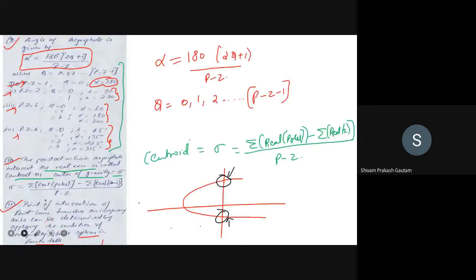Next step, that is step number 7. The number of root locus branches is equal to the number of open loop poles, equal to the number of closed loop poles, which is also equal to the order of the closed loop system, right? Step number 8, the root locus branches terminating at infinity will do so along straight lines given by asymptotes. So we have calculated asymptotes.